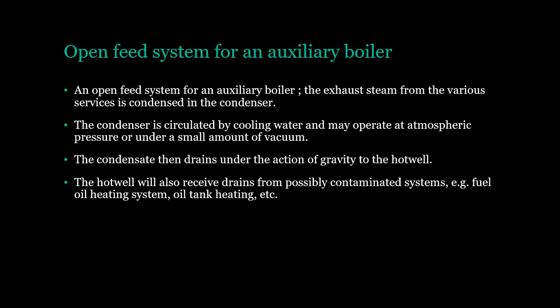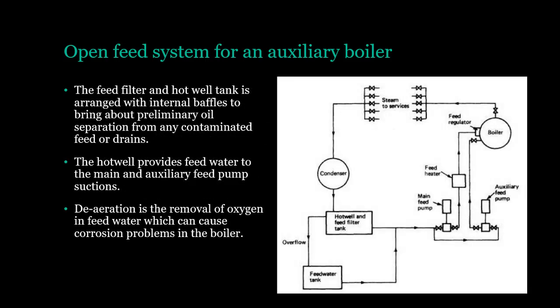Open feed system for an auxiliary boiler. The feed filter and hotwell tank is arranged with internal baffles to bring about preliminary oil separation from any contaminated feed or drains. The hotwell provides feed water to the main and auxiliary feed pump suctions. Deaeration is the removal of oxygen in feed water which can cause corrosion problems in the boiler.